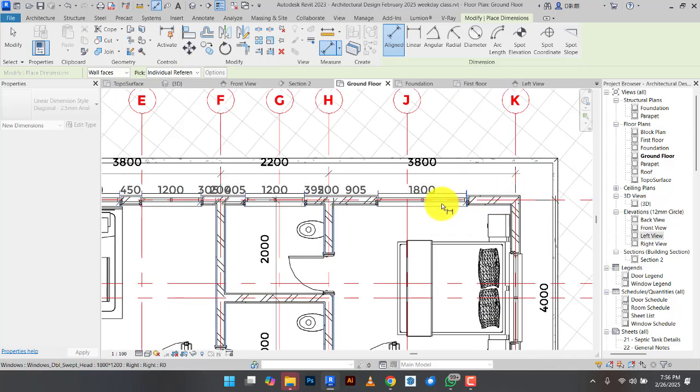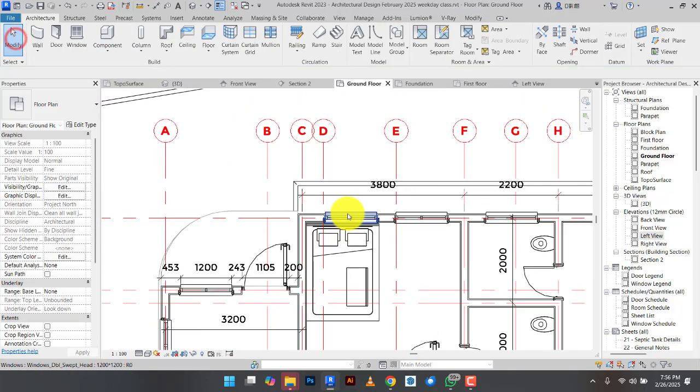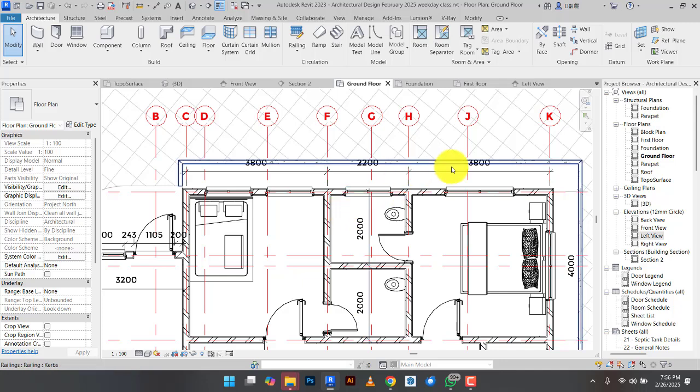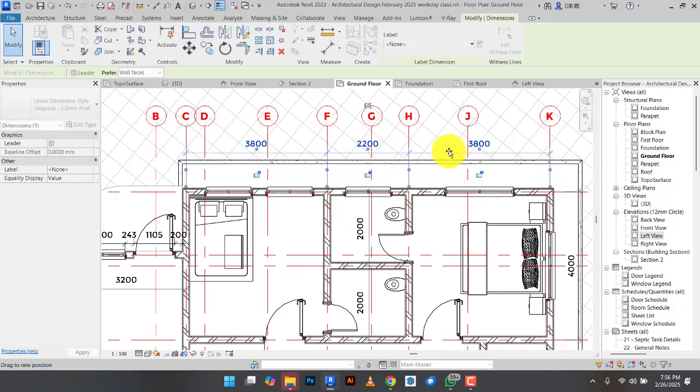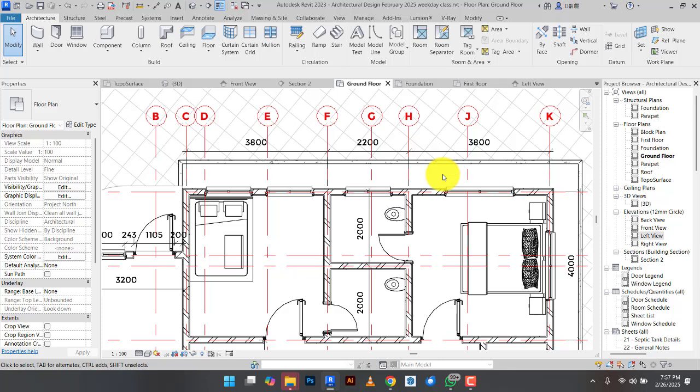Okay, however, instead of clicking like I'm doing, the software can do it for you. Revit can do all that clicking for you. So you don't have to click. You tell the software that you're going to pick a wall, and any window or opening in that wall, it will gladly dimension for you.